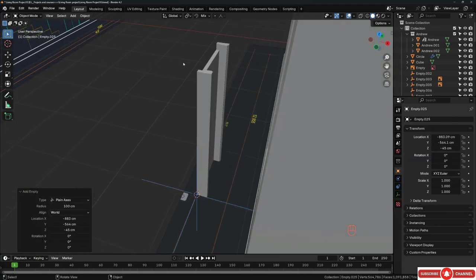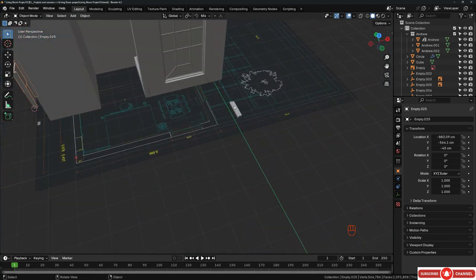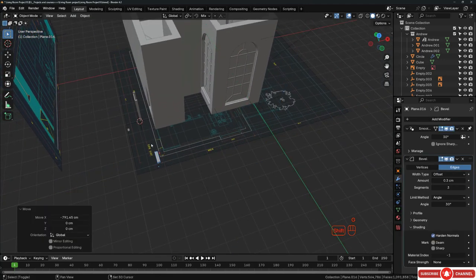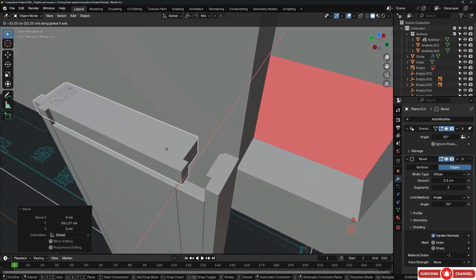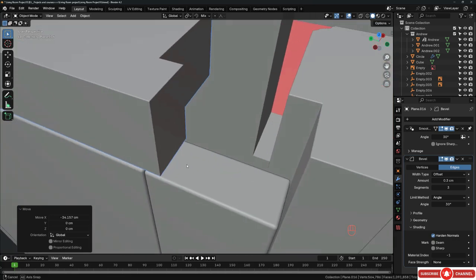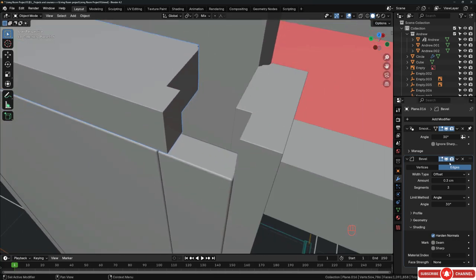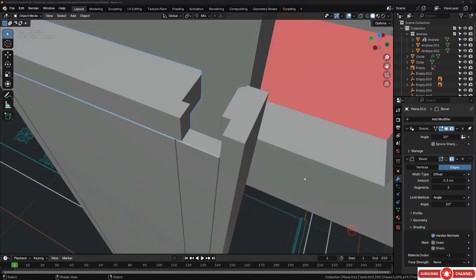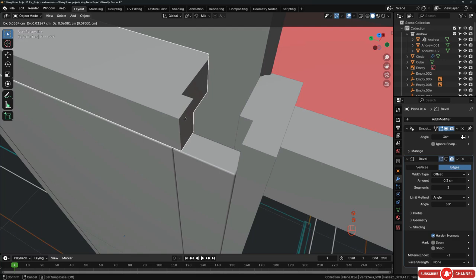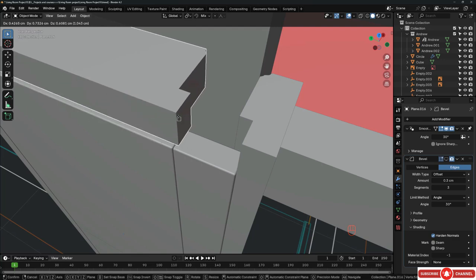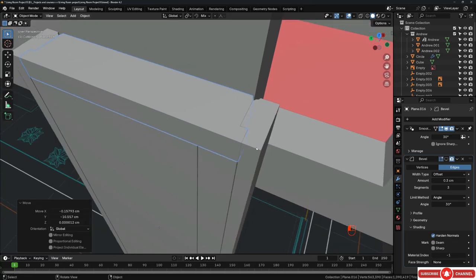And now I will select all of these pieces. And it seems like I forgot to select this one. All right, that's very bad. Let's try to put it in the correct place. All right, let's turn off bevel temporarily to snap this perfectly. After turning bevel off, I will select this piece and then hit G to move and then B to pick a certain point, for example this one, and snap it with this one. After that you can turn bevel on.